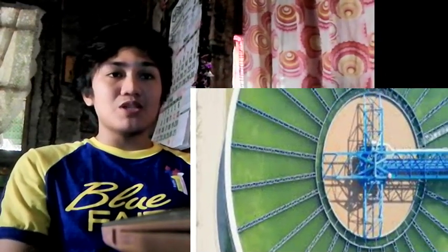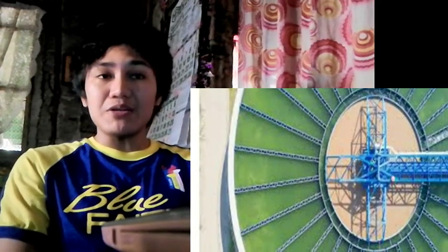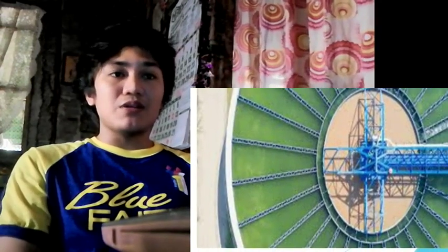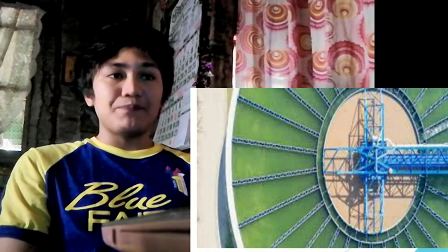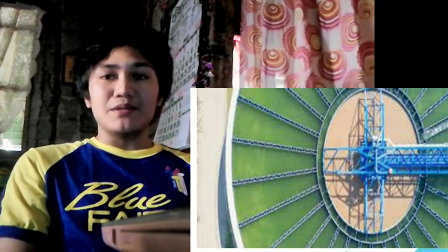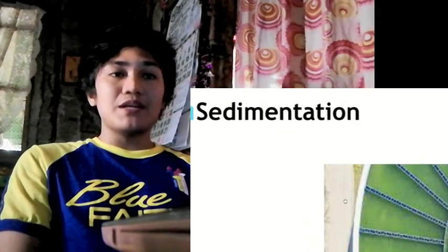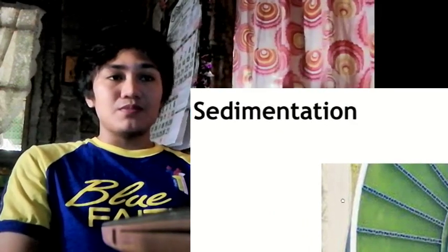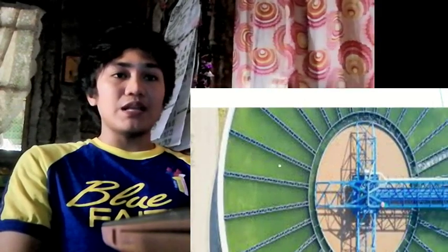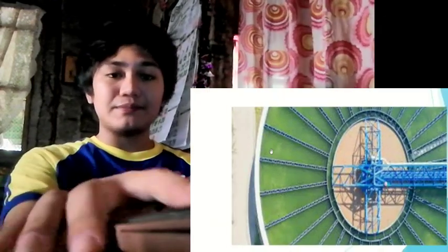Sedimentation basins are usually rectangular or circular, with either a radial or upward water flow pattern. Regardless of the type of basin, the design can be divided into four zones: the inlet, settling, outlet, and sludge storage.